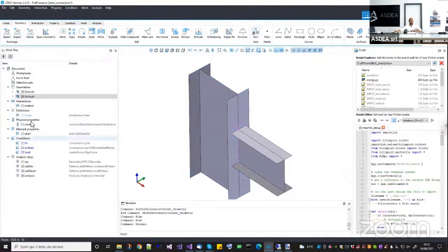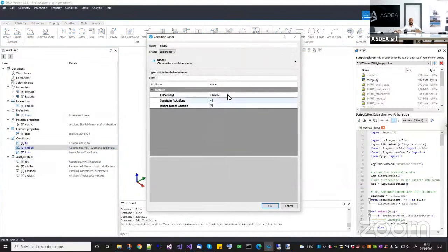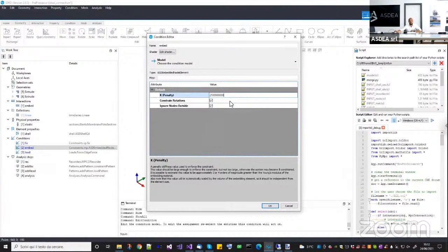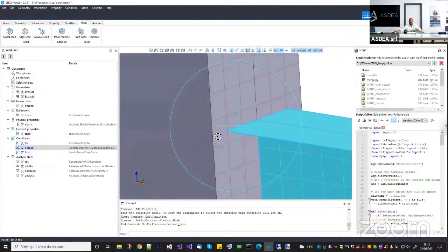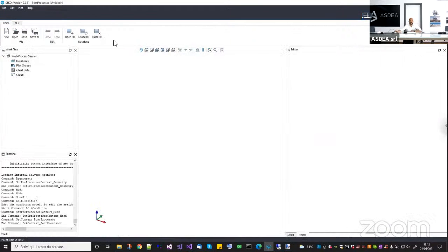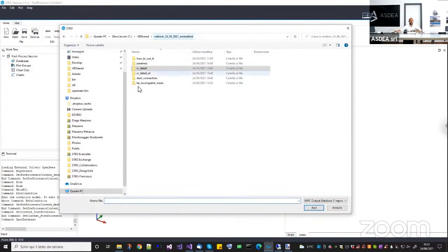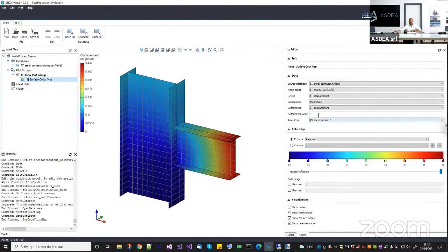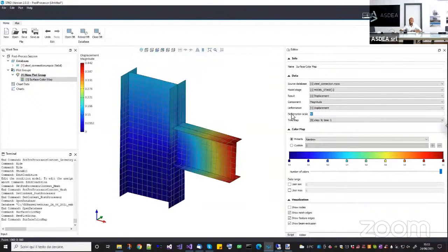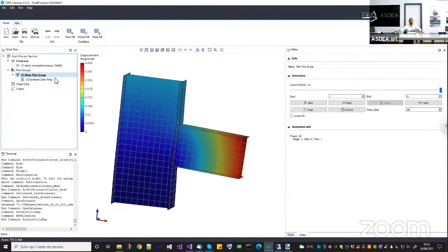So you do that. Once again, you create an embedded condition. You assign an embedded boundary condition. Now this time it is the stiffness of the steel, 3 orders of magnitude more. And you do your own mesh, and as you can see, the meshes are not compatible at all. But when you run the analysis, they will be attached. No, probably also 100 is fine. Oh, too much. Okay. And you can see that they are perfectly attached if you calibrate that number properly.